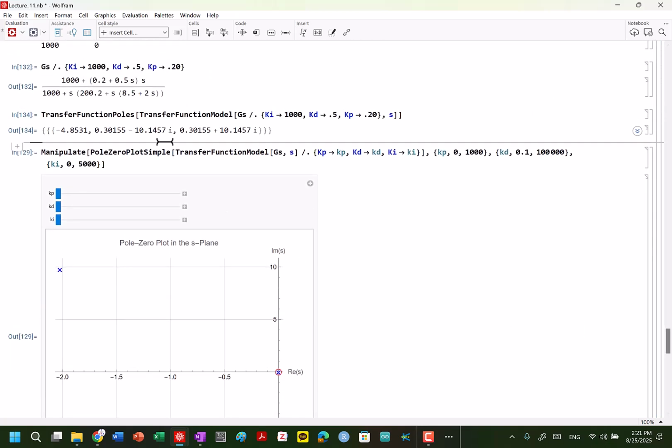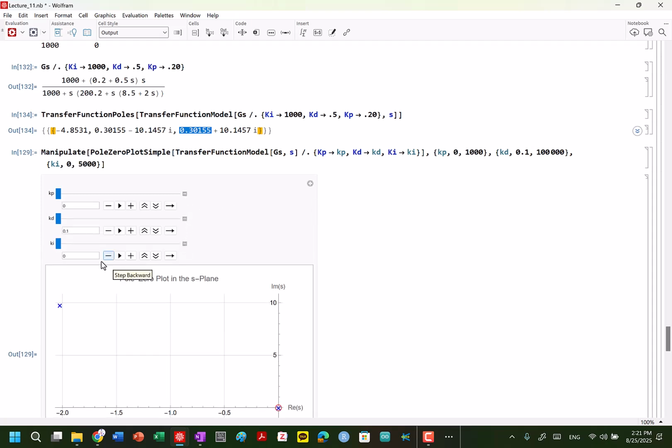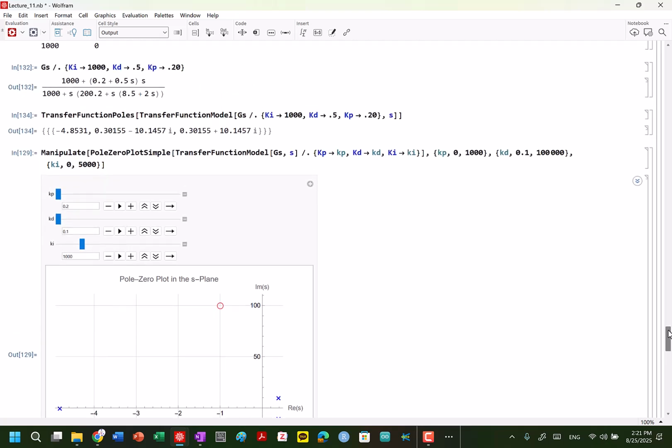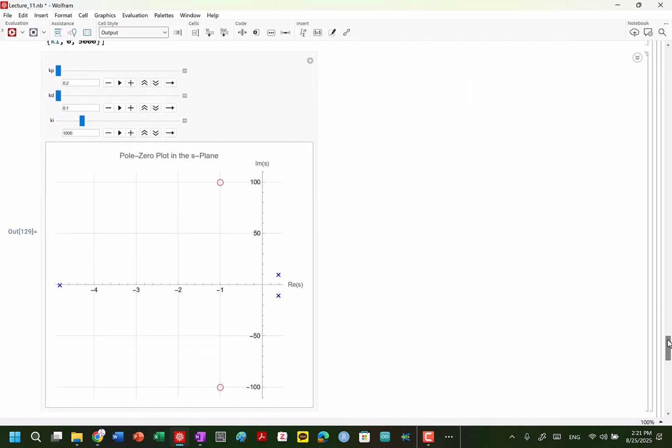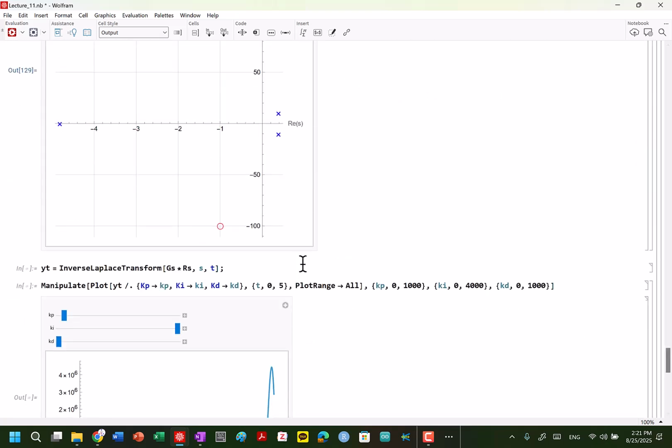So we can see we get positive right here. So positive 0.3, positive here, and now we're kind of in trouble. Actually, why is it 1,000? I want to visualize this. 1,000, and then this is 0.2. There, that's better. I was going to say it looked a little weird earlier, but we can see essentially those three poles now. So we're definitely not stable in this.